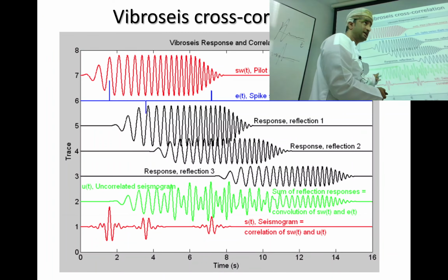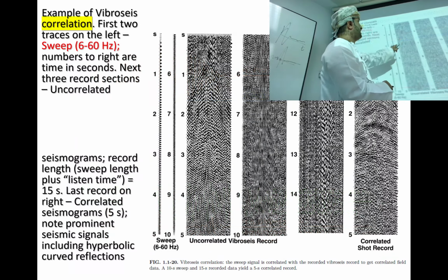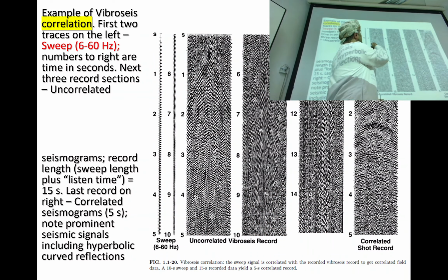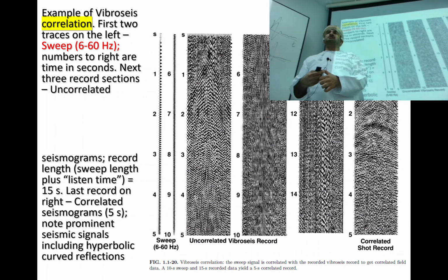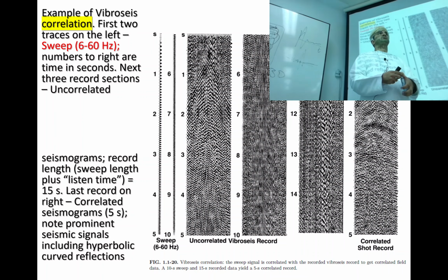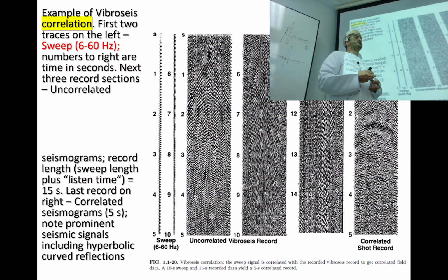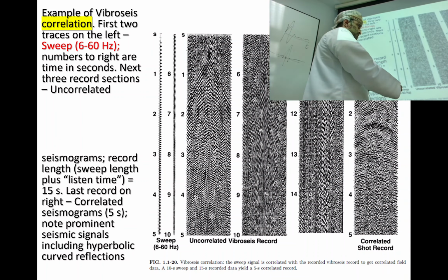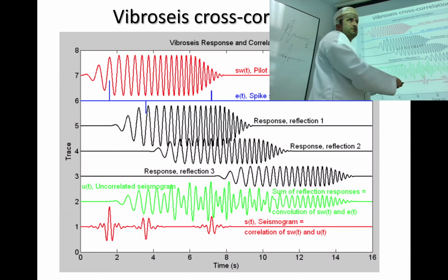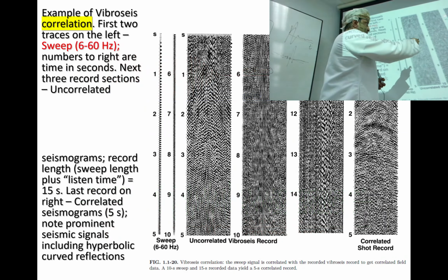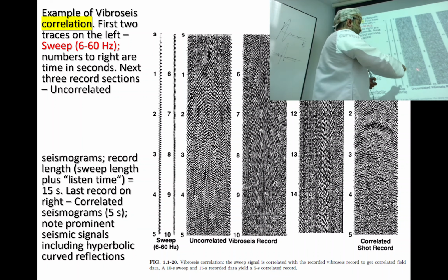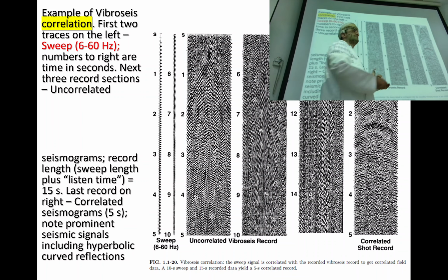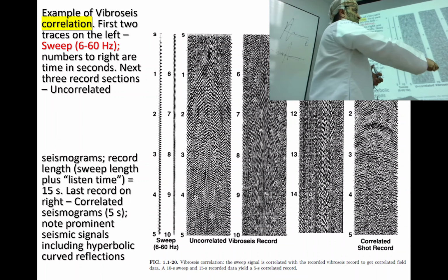It's similar to this. Here I had only one, whereas here I have how many? Many of them, side to side, because each one represents a group of receivers, a lot of geophones, or maybe one geophone. It depends on your acquisition parameters. What do I do, what is the process we said? Correlation. I cross-correlate this recorded data with the sweep. That's the final section I receive.